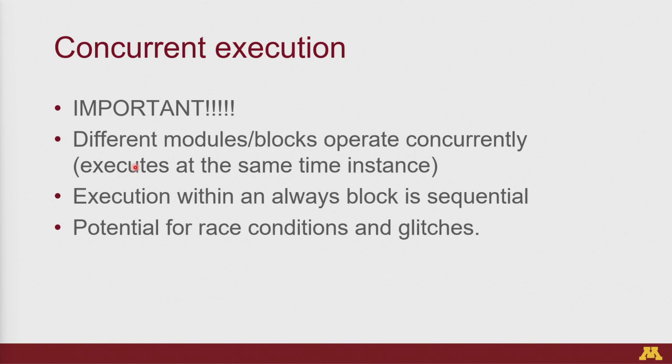The way you think of Verilog is that you're designing actual hardware blocks, right? If you're designing, let's say, an AND gate or a multiplexer, would the multiplexer wait for the functionality of the AND to happen before it does its own functionality? No, right?